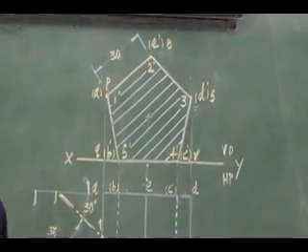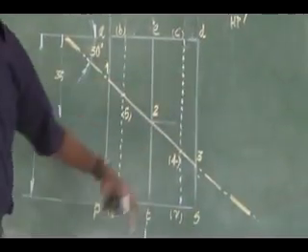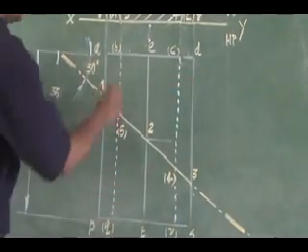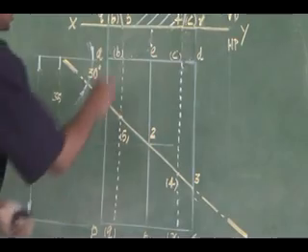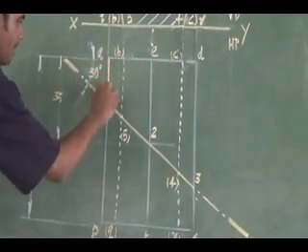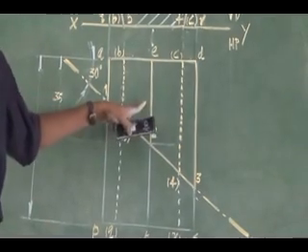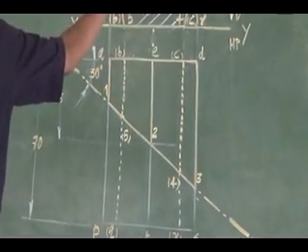So what about my top view, which is the retained portion? The front portion is removed. So the retained portion is this. That alone you have to darken. The retained portion. Right. This is my retained top view. This is my sectional front view.